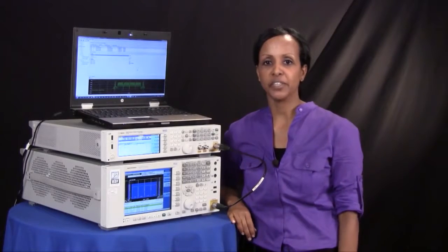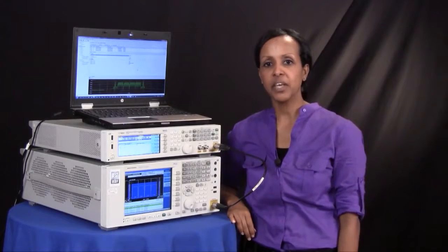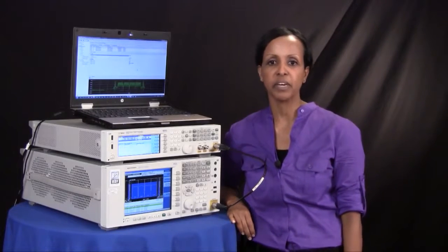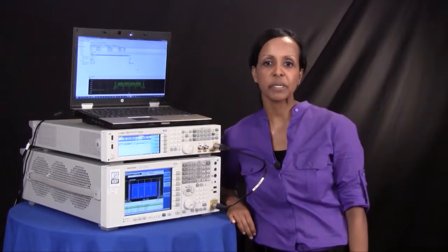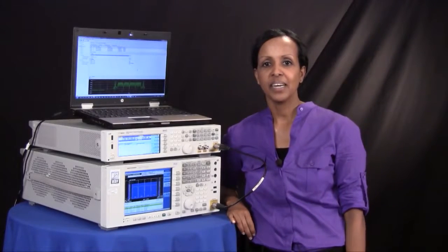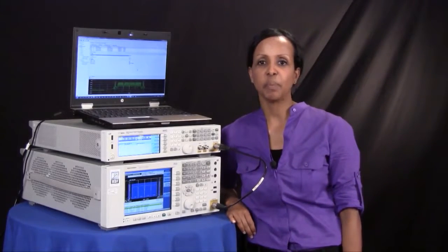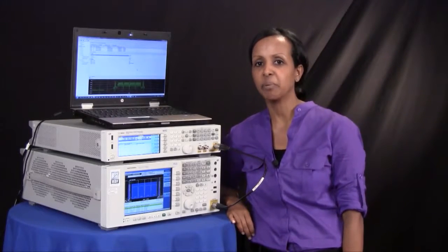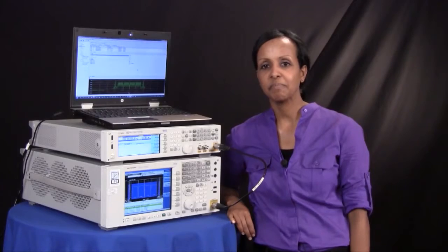Now, a single amplifier is used to transmit multi-carrier, multi-standard signals, and different signal combinations will stress the amplifier differently since they will have different peak-to-average ratio. Agilent addresses this challenge by providing statistically correct MSR waveform needed to test amplifiers and other components.